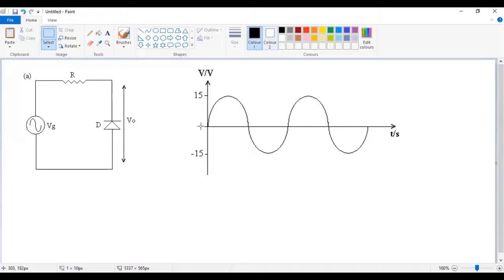I want to progressively go to more advanced circuits. So we've seen if you have a waveform like this applied to this diode circuit, basically what we want to find out is for what part of an input waveform is this diode behaving in forward bias mode. This is where you will short circuit the diode if it's assumed to be ideal, and then for what part of the waveform is the diode actually reverse biased, which is when you will open circuit it.